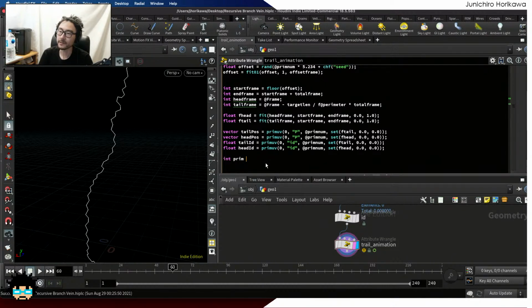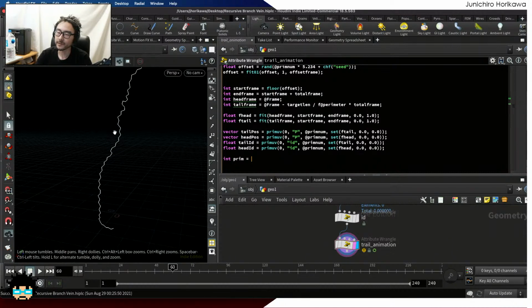So initially I'm going to create a new primitive as a new trimmed out curve. When I say trimmed out, I am not going to reuse the current primitive, but instead I'm going to recreate a new one, and after we create a new one, I'm going to remove this original geometry because that's easier for creating a custom geometry. Removing points is sometimes a bit too difficult to control, especially when you want to add the new points on the end for a polyline. So that's the method that I'm going to use.